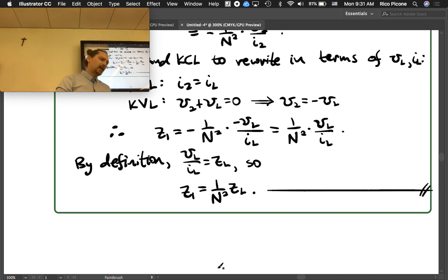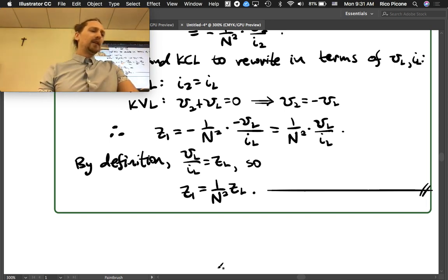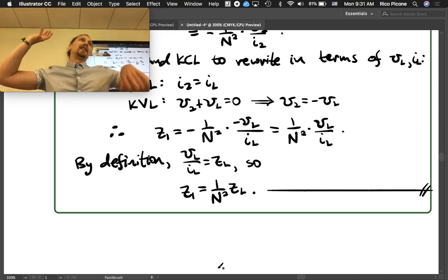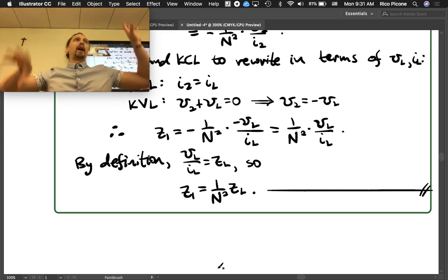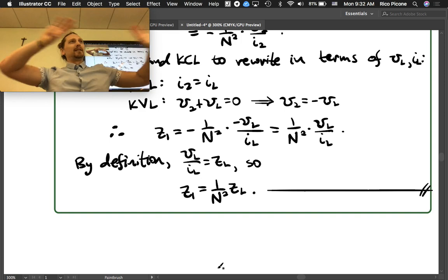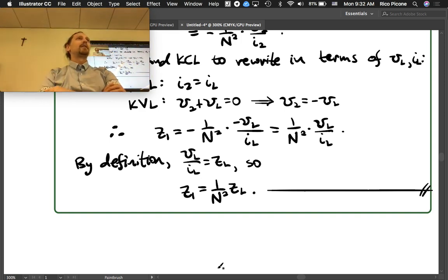And it can also be used to isolate one circuit from another circuit in terms of the DC component, because the DC part is completely ignored by the transformer, right? So you could have two circuits with completely different DC components, so there could be a different ground even. But they'll transform the AC part just fine through them. So they can kind of interact in an isolated way. So they're useful for that as well.